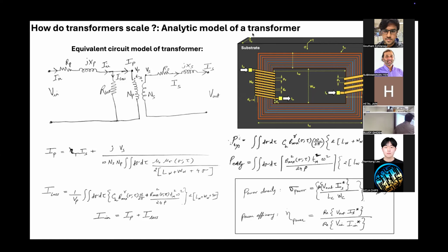And so what we are doing is we are starting from the load side and then calculating everything up to the source side, okay? So we start by assuming, say, the output is 1 volt, 1 amp. So say a chip that's operating at 1 volt, drawing 1 amp. So this is at a fixed load condition. And then you essentially back calculate all the other parameters. So you start with 1 volt, 1 amp, and then using this impedance, you calculate the voltage here, then the voltage here, and then you calculate the currents here, and then finally you calculate the input voltage, okay?